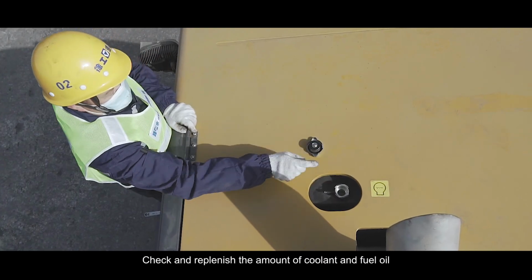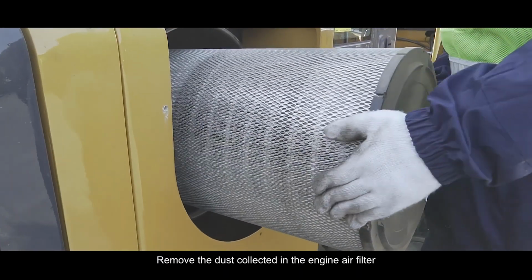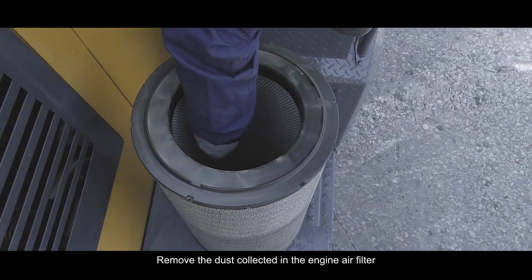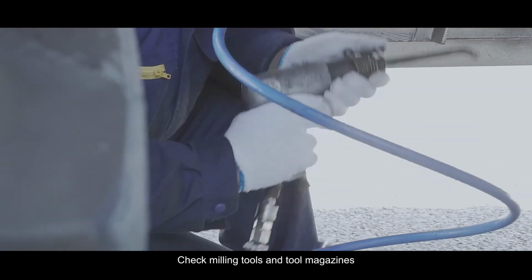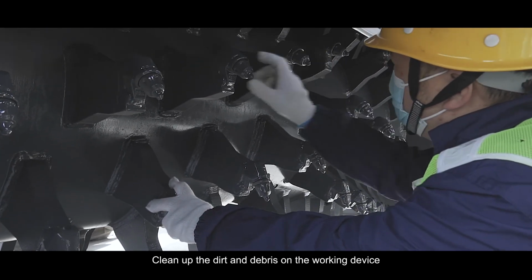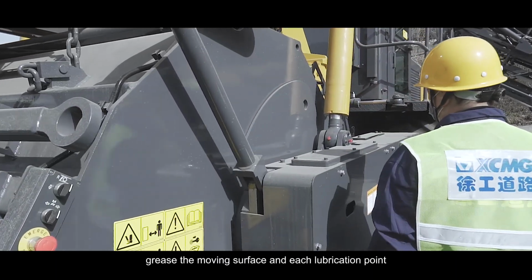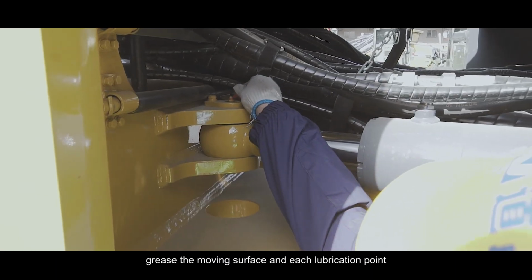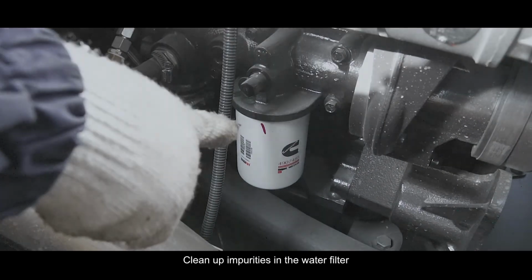Check and replenish the amount of coolant and fuel oil. Remove the dust collected in the engine air filter. Check milling tools and tool magazines. Clean up the dirt and debris on the working device. Clean the exposed surface. Grease the moving surface and each lubrication point. Clean up impurities in the water filter.